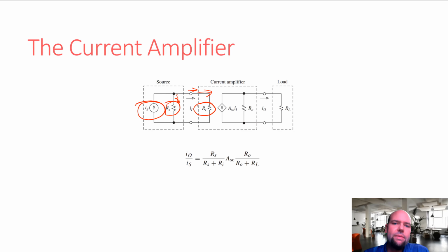And that's sometimes a little strange for students to think about: okay, we have a signal and we want to have a 0 ohm load. We want to have that signal going into a 0 ohm load. It's usually a little weird because basically you want a short circuit. You want to have that input connected to a short circuit. Well, yeah, you do in the case of current, when a current's your signal, because currents love short circuits. If you have 20 milliamps, 20 milliamps would love to flow through a short circuit. It takes 0 volts for 20 milliamps to flow through a short circuit.